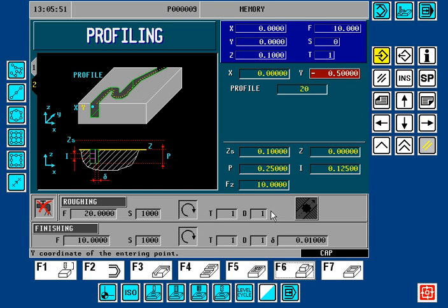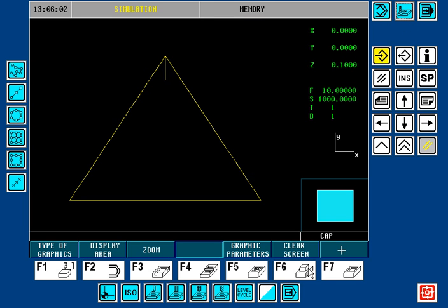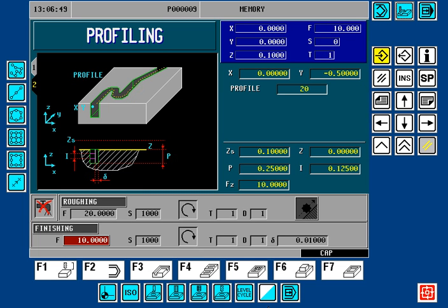But once you activate the cutter compensation, left, go back to graphics, cycle start, you can see that we're going to gouge the part up here because we've started at a nested corner. Under these circumstances, your best solution is to start in the middle of a line and not in a nested corner. This concludes our discussion on nested corner start end.